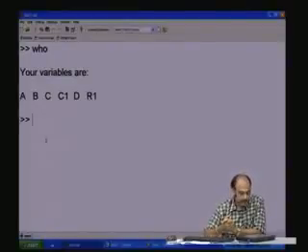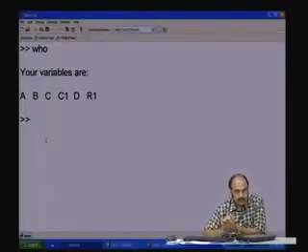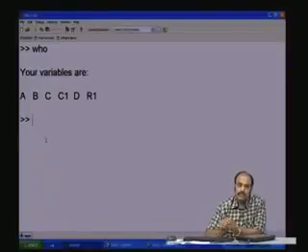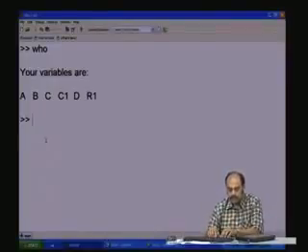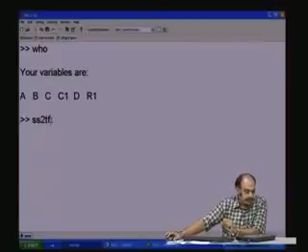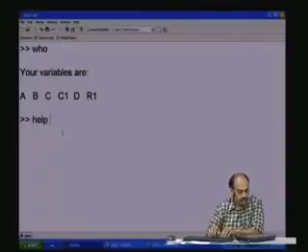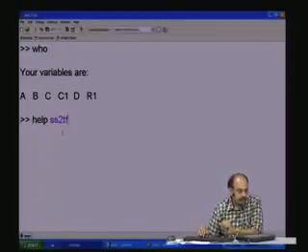Now, what do we want to do with these variables? These variables are in the state space form. Now, we want to convert it into the transfer function form. So, we use one function in MATLAB called state space to transfer function form, that is SS2TF. So, this means state space to transfer function form. The syntax is very simple. In fact, MATLAB is very friendly. If you want to know the syntax of this, you just have to type help ss2tf. So, you get the syntax of the particular function command.